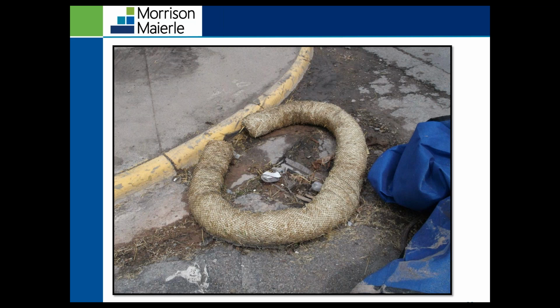This photo right here shows a straw wattle that's used to protect an inlet. This BMP is not installed correctly and it's not adequate for the pollutant source. Again, like the previous skid steer, the straw wattle is not staked or trenched, which is resulting in sediment discharging into that inlet.